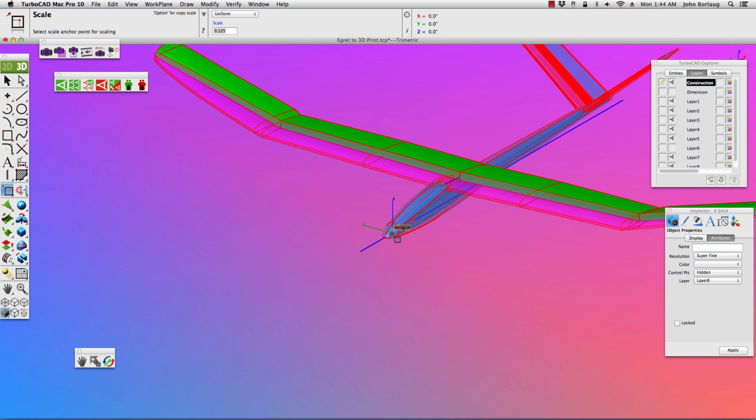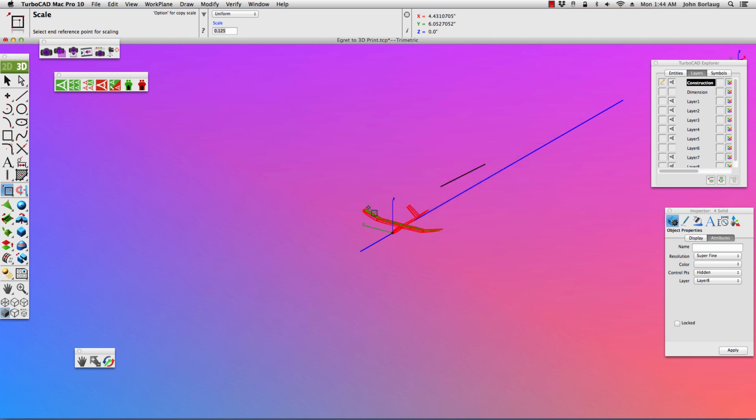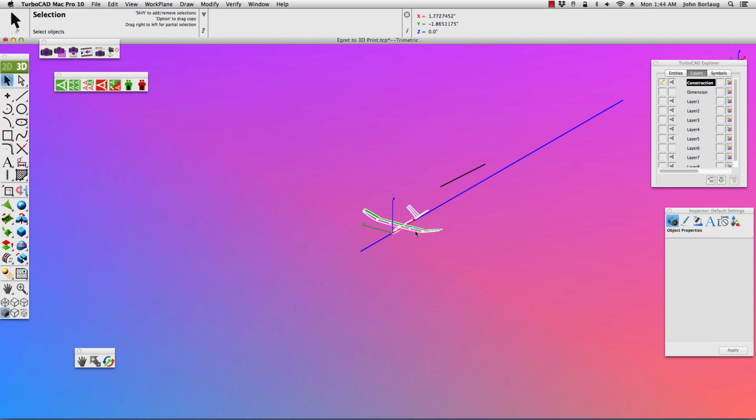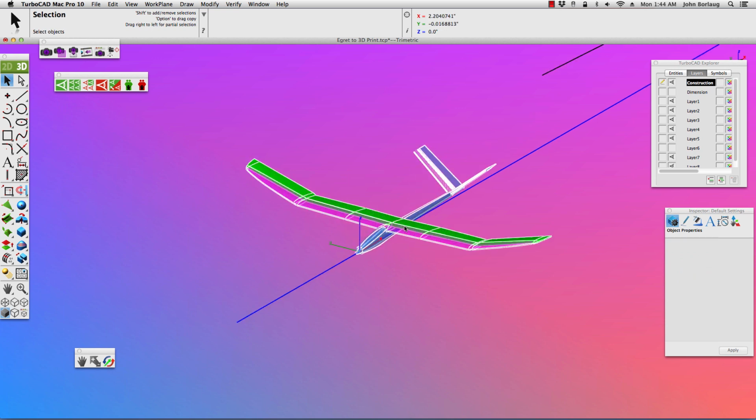The nose cone comes into the negative by 1.5 inches, so hitting the anchor point at the origin, and then I left click again to start the reference, and then because I punched in my 1/8 scale here, now I just simply hit enter, and there we have our reference lines that are maintaining their size.